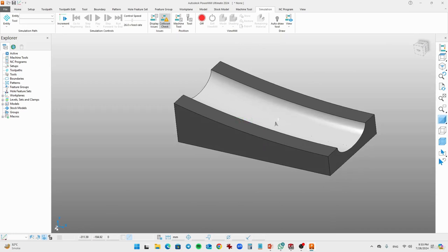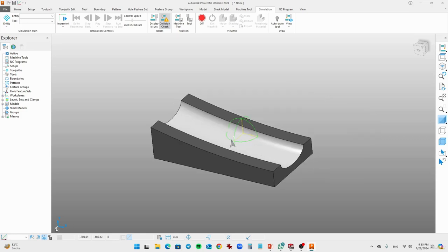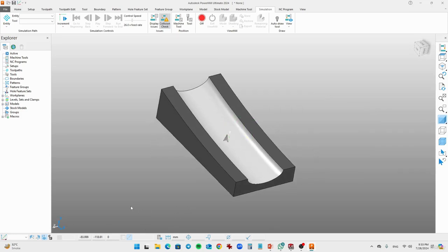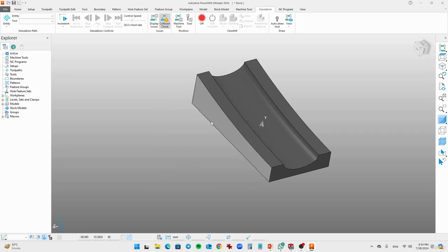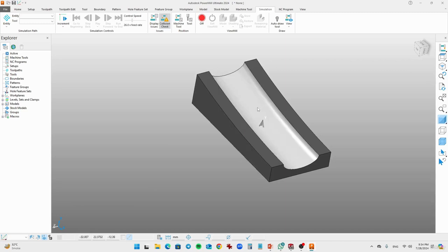You see that this is the z-axis, which is in a light color. Let me show you right here. You see that the cursor shows the z-axis on this side, but I want the z-axis this way. You can either create a work plane and activate it, or you can rotate your model.